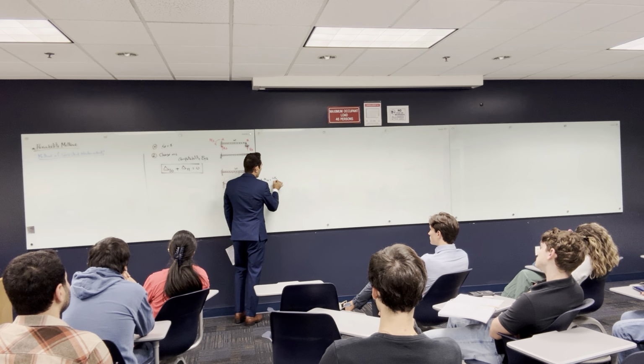Point 1 is this point, because sometimes you are going to have multiple points, so you're going to have 1, 2, and 3. And O means that this comes from the original loads. Like you have your system with the original loads, so anything with the original loads is going to have O. Delta 11 means that this is at point 1, and the other 1 means the unit load 1.